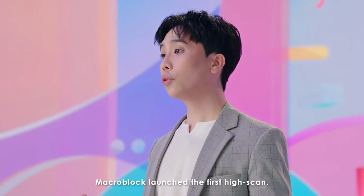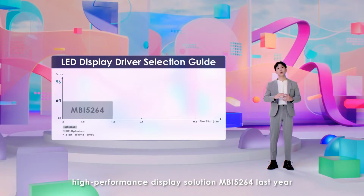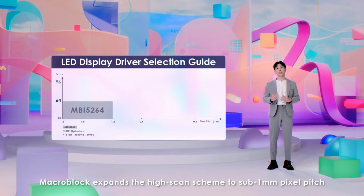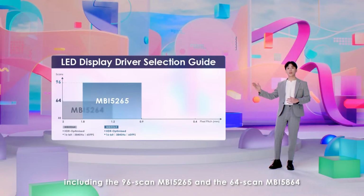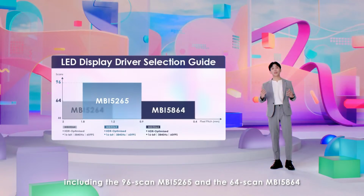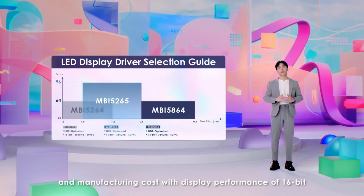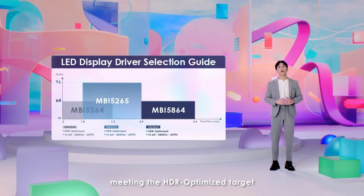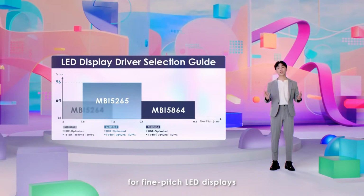Let's sum it up. Macroblock launched the first high-scan, high-performance display solution MBI 5264 last year. In 2021, Macroblock expands the high-scan scheme to sub-1 mm pixel pitch, including the 96-scan MBI 5265 and the 64-scan MBI 5864. All three products effectively lower driver IC counts and manufacturing cost with display performance of 16-bit, 3840 Hz refresh rate, meeting the HDR-Optimized target. These are Macroblock's high-performance solutions for fine-pitch LED displays.